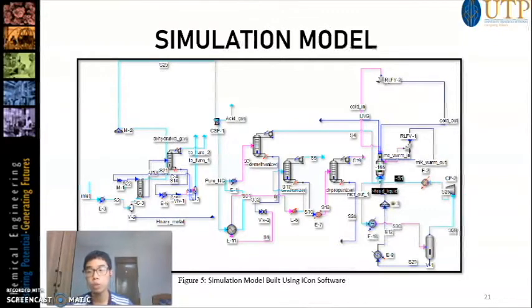Now, the stream is ready for liquefaction. Methane was first separated by using a demethanizer. This is because separating a bigger chunk from the stream is more effective than separating it later. Ethane and propane were also fractionated to be sold separately to increase revenue.